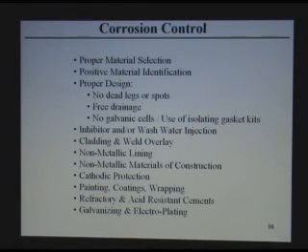It is an instrument that goes over the metal and welds and tells you it is 5 chrome or stainless steel. If it meets specification, then the equipment uses the proper specified material. If it is not, then you have to replace it.